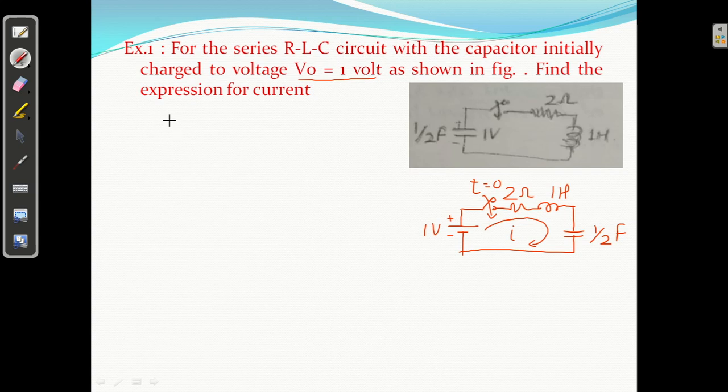So please see here, before t equal to 0, I L0 minus equal to IL0 plus equal to I0, and similarly VC0 minus equal to VC0 plus equal to VC0. Now I am assuming in this diagram the switch was open. If the switch was open, what was the current flowing? 0.